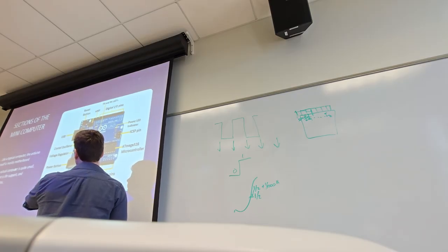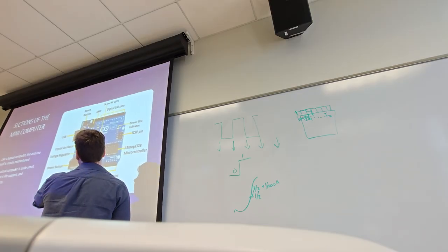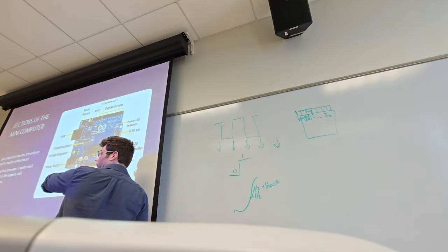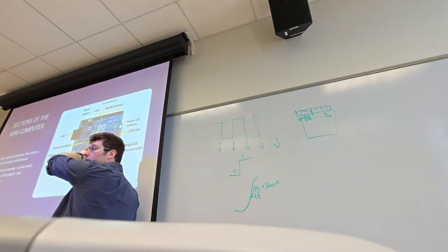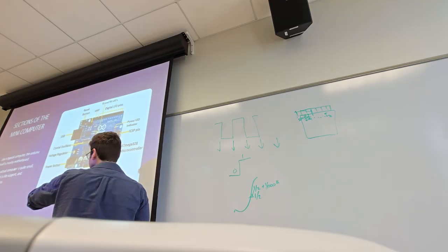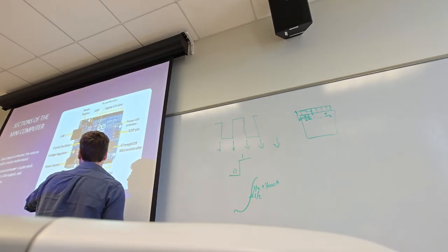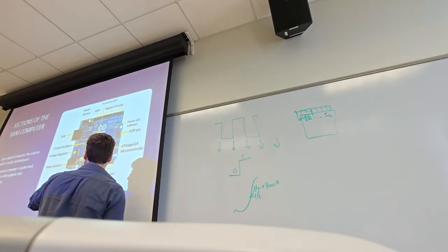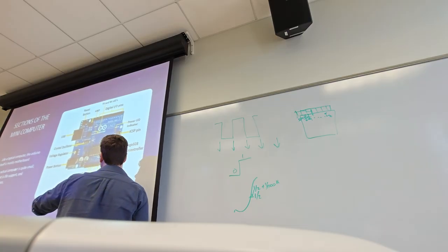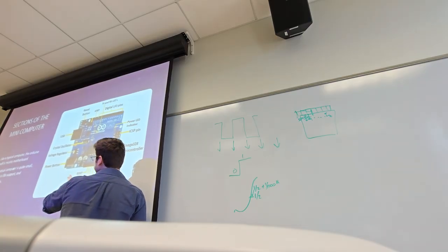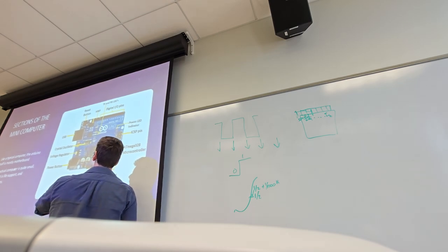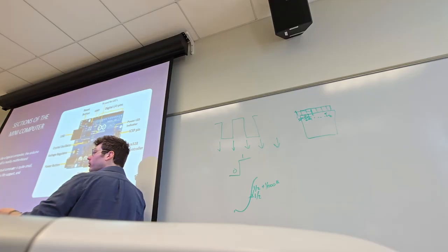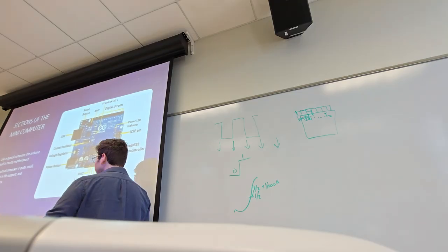There's actually, really conveniently, one of these pins that puts out 3.3 volt power all the time. This is a 5 volt board, so we always power it with 5 volts or above. I'll explain that in a second. But we have a nice clean source of 3.3 volt power, really commonly used for sensors. Sensors love 3.3 volt power because it's really clean, it's very stable, and it doesn't necessarily have to be high power. It's power efficient, all that good stuff.